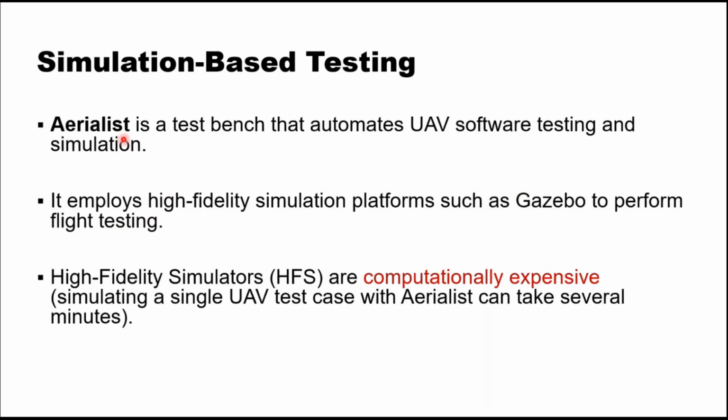Okay, so this is currently simulation-based testing. We generate test cases, then we simulate them. We use the earliest, which is a test bench that automates UAV testing. And this test bench uses high-fidelity simulation platforms such as Gazebo to perform flight testing.